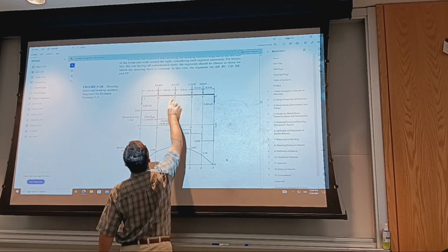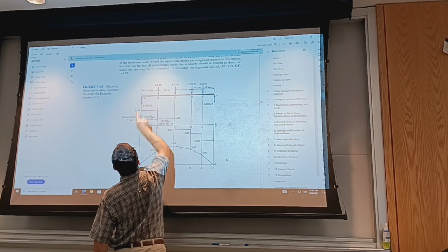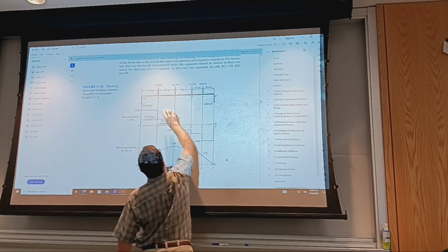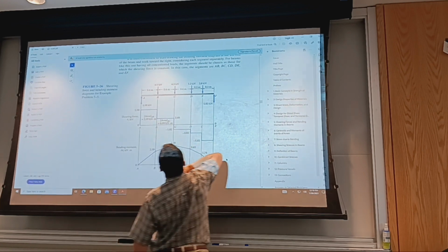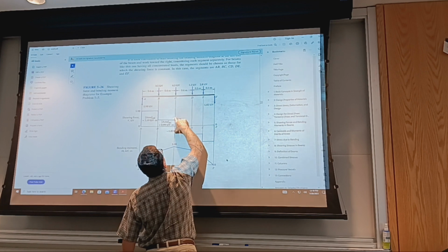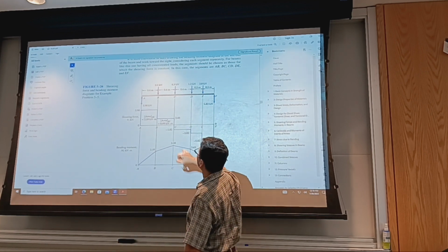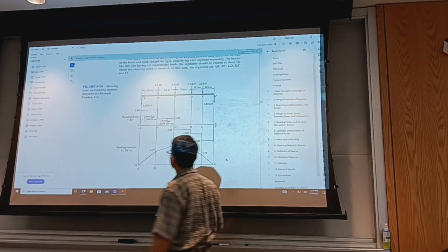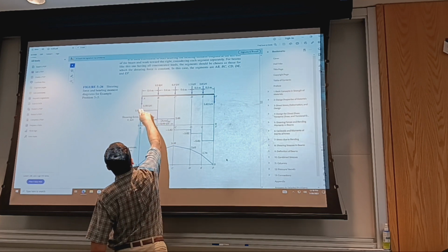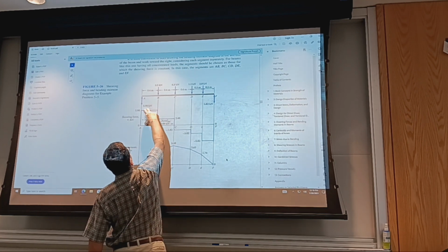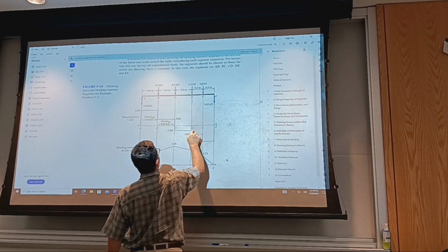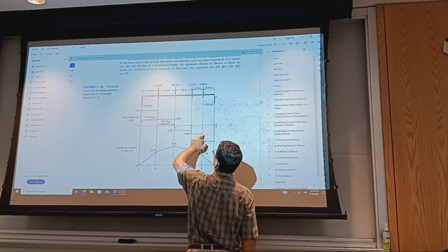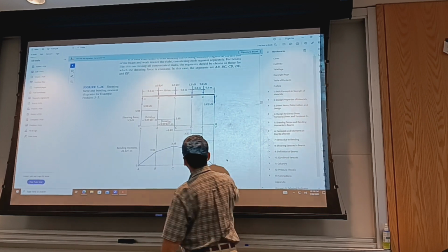When it comes to external loads, though, if the external force is up, the diagram moves up, and if the external force is down, the diagram moves down. All right, so drop by the amount of 3.5 kilonewtons, drop by the amount of 4.3, and it can be both positive and negative. Likewise, moments can go both positive and negative, but you correlate the slope with the shear diagram, more slope, less slope, both positive, and then it switches to a negative slope, and then increased slope, also negative, and the most abrupt section of the diagram.